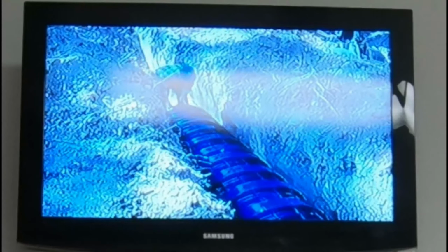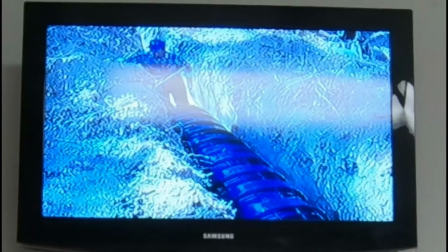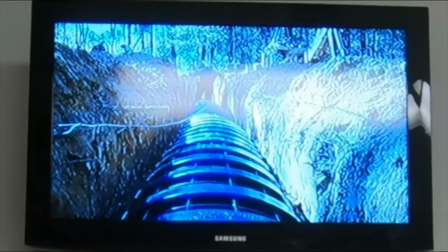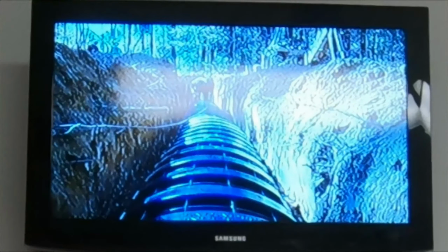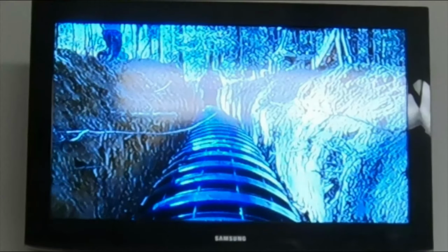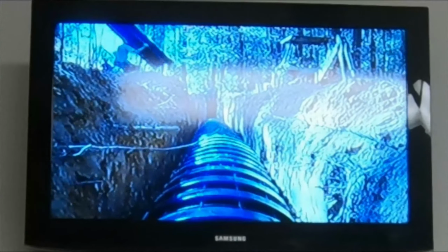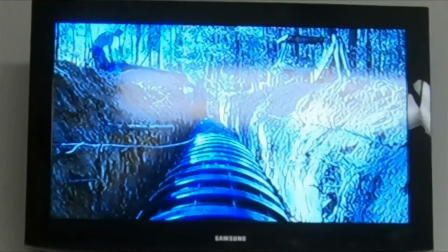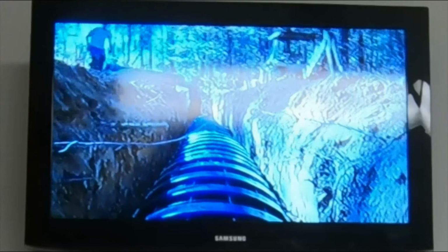The plastic is shaped to form a hollow structure with an exposed bottom area for infiltration of effluent into adjoining bottom and sidewall soil areas. Chambers may be of different sizes and configurations to obtain desired surface area. However, on average, each panel is 6 feet, 3 inches in length.